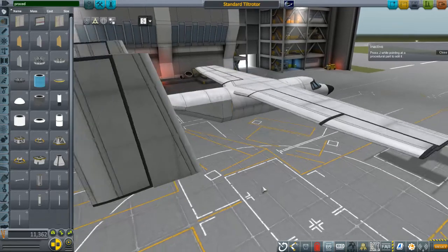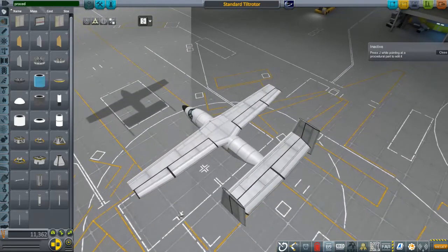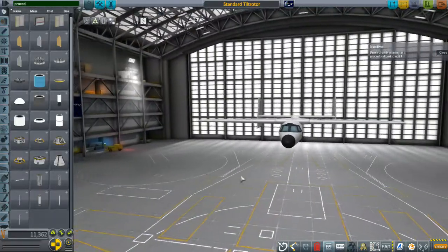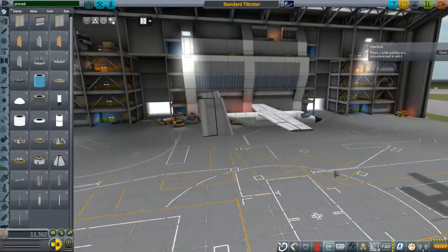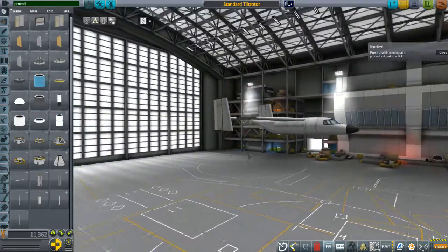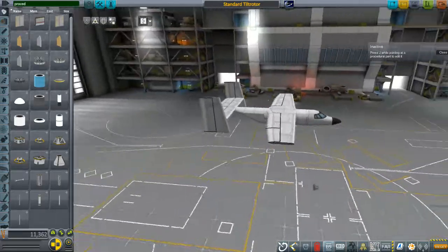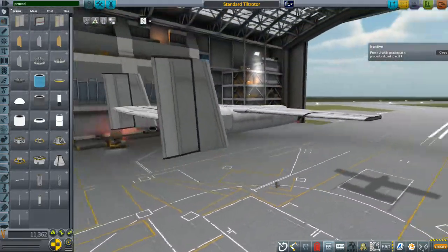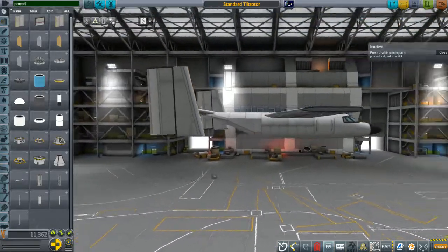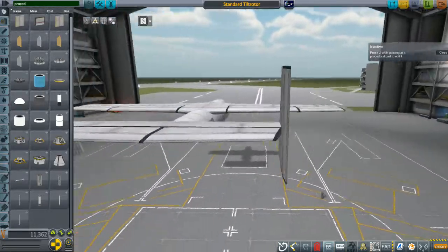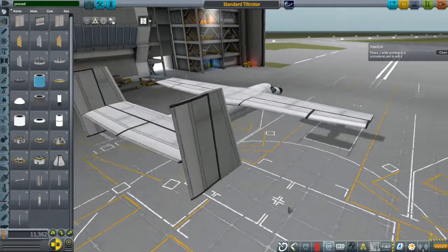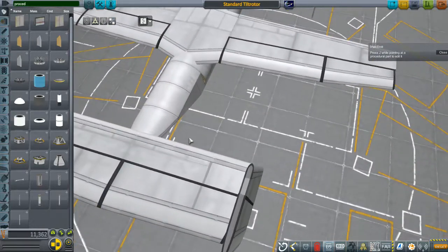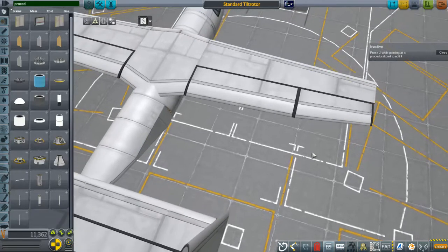This is important because when the engines are configured like a helicopter, they have to have a thrust-to-weight ratio significantly greater than 1, or all you do is sit on the ground moving air. So when you convert all that thrust to a forward flight vector, or even a partial forward flight vector, that's all the acceleration in the world. So you can imagine that you need to keep from going to crazy high speeds when only in 45-degree flight.